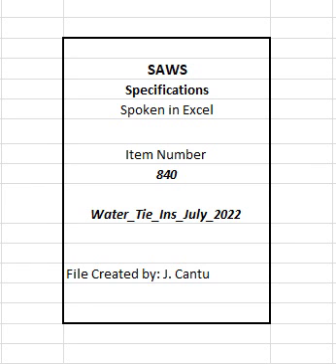4. American National Standards Institute, ANSI. A. ANSI A21.11/AWWA C111, Standard for Rubber Gasket Joints for Ductile Iron Pressure Pipe and Fittings. B. ANSI/NSF Standard 61, Drinking Water System Components, Health Effects. 5. American Society for Testing and Materials, ASTM International, Pressure Pipe and Fittings.